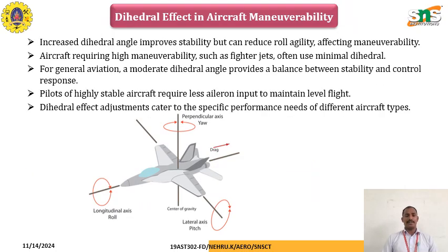Coming to the dihedral effect in aircraft maneuverability, an increased dihedral angle improves stability but can reduce roll rate, affecting maneuvering. Aircraft requiring high maneuverability, such as fighter jets, often use minimal dihedral.